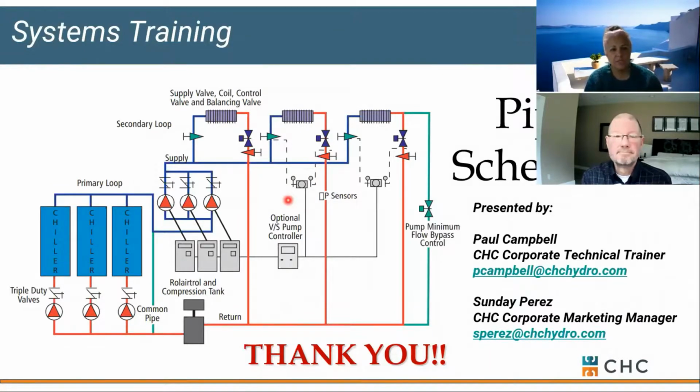Okay, and one more question. How often is imbalance of flow really a problem in systems? Pressure drop changes with the square of flow, and if equipment is closely placed, 2 or 3 boilers on a skid, then the piping pressure drop difference should be minimal between them with a full-size header. It seems to me that flow imbalance would be minimal in this case. I can definitely see more of it with equipment which is spaced farther apart.